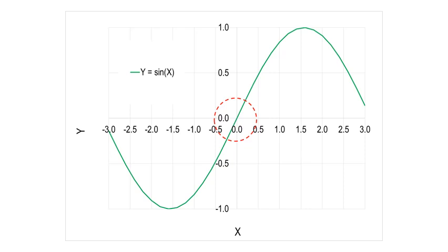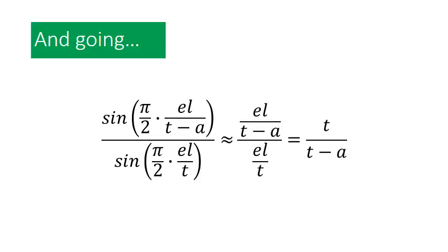Now, I've already specified that if we're thinking about a ductile material with low yield strength, where we've blunted our crack and have a large plastic zone, our elastic ligament is going to get smaller and smaller. So I propose that because our elastic ligament is smaller in this scenario, because we're looking at blunt flaws, ductility, and deep plastic zones, we should be able to use this relationship to effect. It turns out that accomplishes quite a lot.